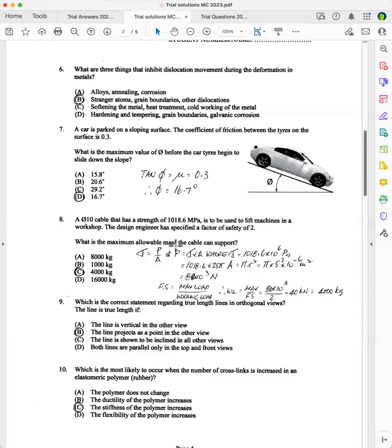We're looking at the mass the cable can support. So you put the formula down here that you get in the formula sheet, and you were after load, which will convert to mass later. And so the load is equal to stress times area. Data here. Make sure that you show the formula for area, substitute here. And I haven't put 10 to the 6, 10 to the minus 6 in here because they cancel.